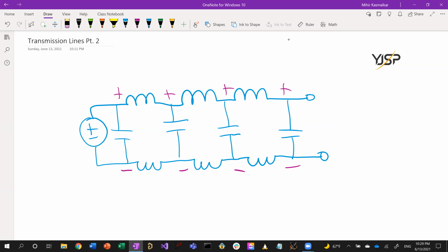And so at this point, there would be a decrease in current, but the inductors don't want a decrease in current because inductors resist changes in current. So what each inductor, which has been charged up, is going to do is discharge into the capacitors. And so this capacitor is going to actually acquire twice the initial charge from the charge that's just being dumped onto it by the inductor.